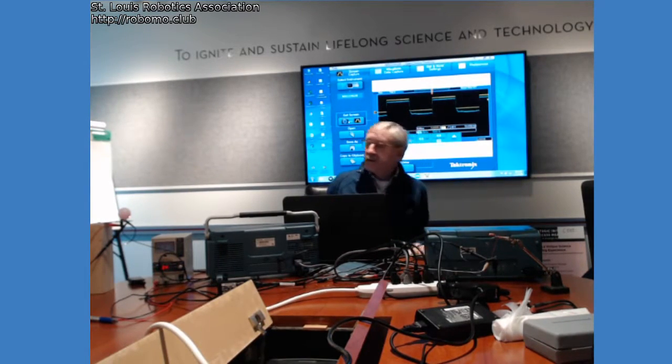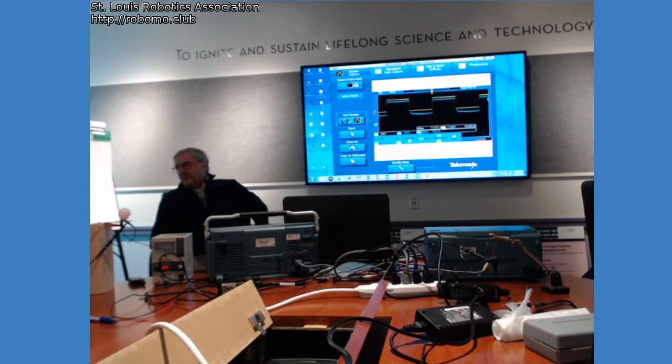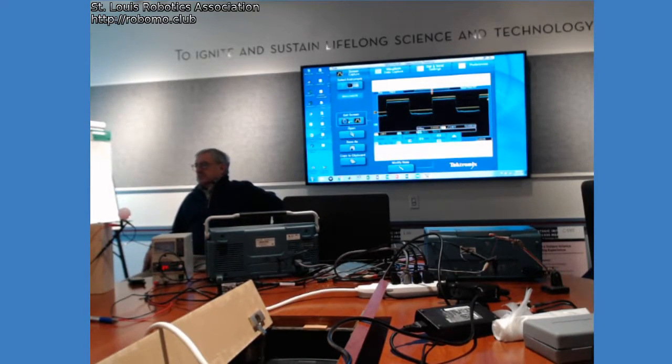I talked to Sam about doing some of this stuff. What I was doing with the photodiodes is trying to amplify the signal. Yeah, you can do that, but the biasing is a lot simpler. Sure, because the sensors I'm looking at only get you a couple hundred millivolts with really strong light on them.